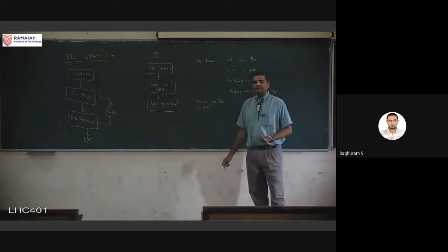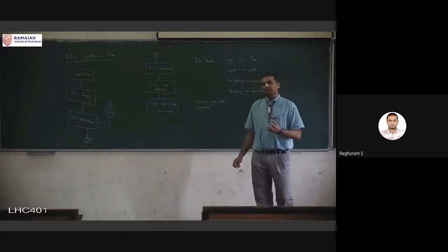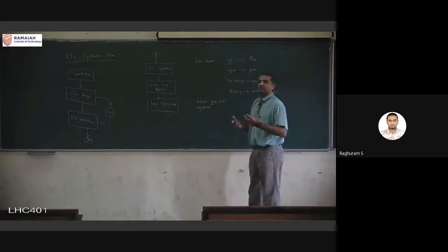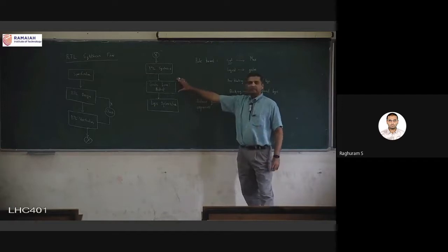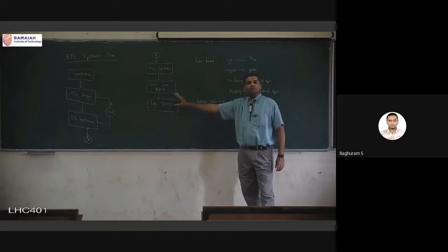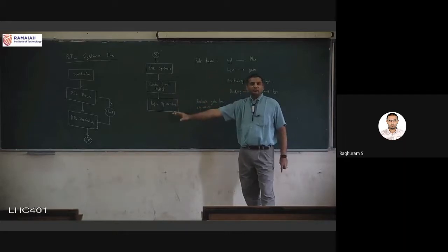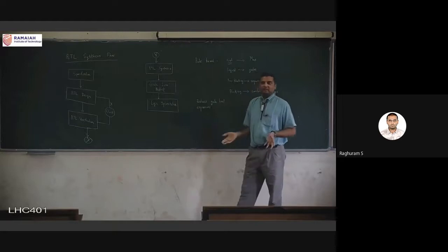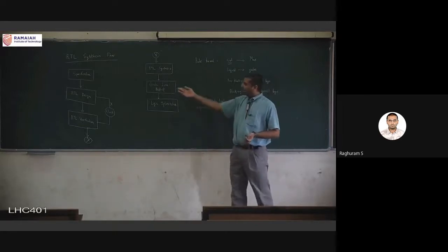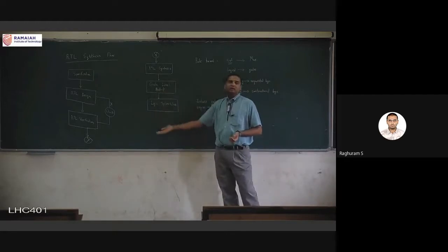But what it does is it reduces the gate level description. Suppose I have some function in this stage, I have the gate level netlist, but it has some 25 terms in it. Suppose I can reduce that to a function with just say 18 terms, because the other terms were either redundant or they were in such a way that they are never coming into the picture, etc. All those are made into an optimized form at the end of this stage. So this is the final gate level description.